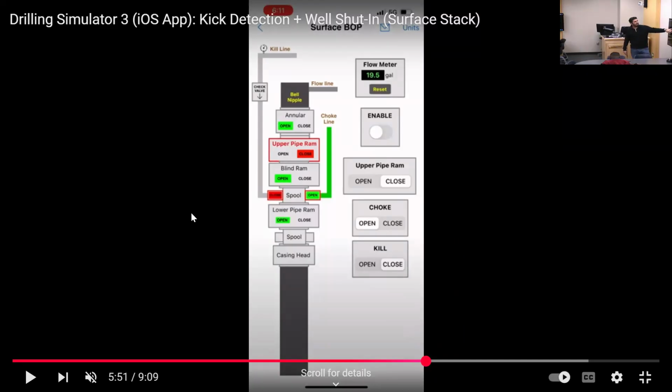Basically, you have to have a way for the fluid to go in and a way for the fluid to go out. You tell it, don't go out through the mud return line, which is open to the atmosphere. Go out through the choke line so that you can hold pressure. That's what you are doing by opening the choke line. That's why you close the BOP, and you make the drilling fluid coming out go not through the mud return line, but through the choke, so you can hold pressure.